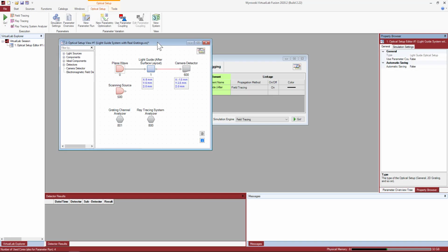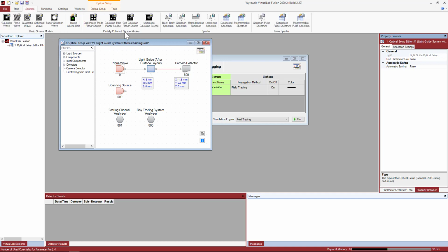Next up is the simulation of partial temporal coherence. So far we have been working with purely monochromatic sources, and now let's take a look at the different strategies available to tackle that side of things, to simulate sources with partial temporal coherence. Let's start with a rigorous way of doing things, which requires generating a wavelength spectrum for our source.